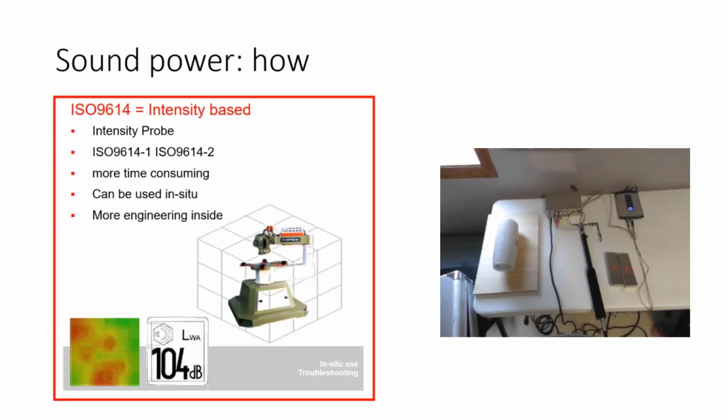So there's a couple ways you can measure sound power with sound intensity. We can measure sound intensity and we can also measure sound power. And I talked about how sound power is the source. And the way you can do that is you can build usually a little grid. And this little grid you build around your test article. There's a standard specifically that defines this. It's the ISO 9614 standard. This will give you sound power. You can also use this grid method to measure sound intensity and sound localization.